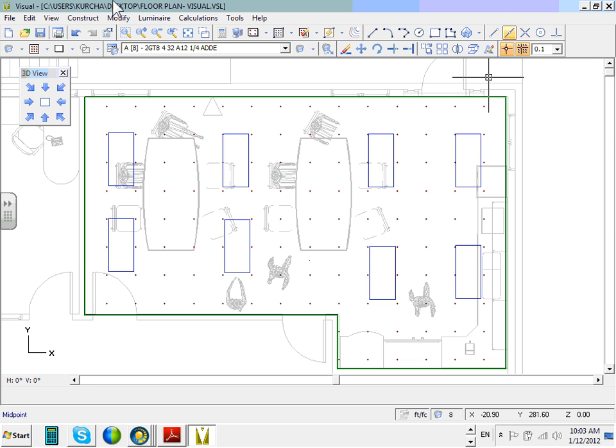All right, so here's what I'm going to tell you. Everybody place some type of fixtures similar to these. Okay, now I have no idea where I put my fixture, these 3Ds. Did they put them at 10? They should be at 10 because they're recessed. If you put them at 11, guess what? You put them above the ceiling, so they will have no calculation. I have no idea now. Can you guys give me a thumbs up that you placed some fixtures? Okay, all right, now I have no idea what the height was, right? We should have paid attention to the height before.